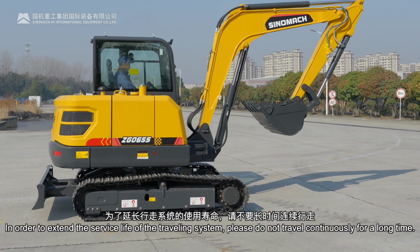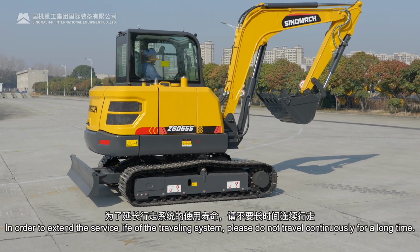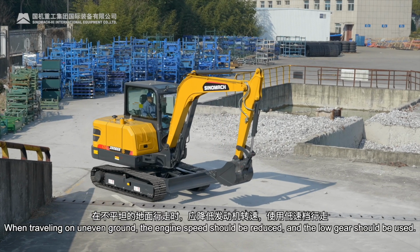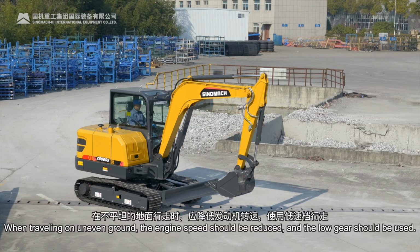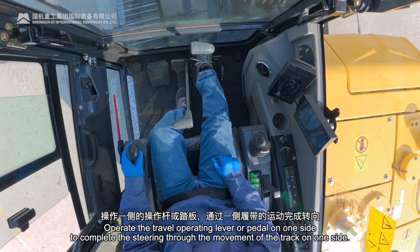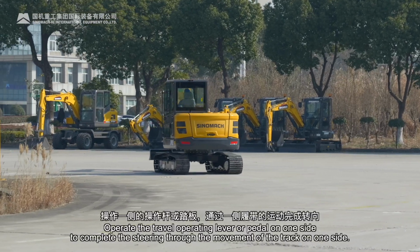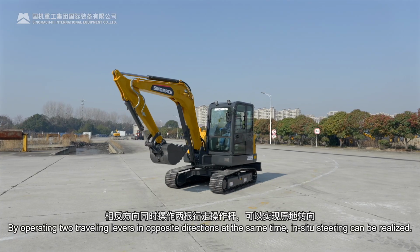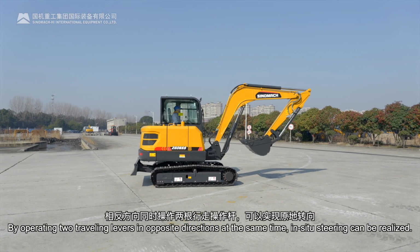In order to extend the service life of the traveling system, please do not travel continuously for a long time. When traveling on uneven ground, the engine speed should be reduced and the low gear should be used. Operate the travel operating lever or pedal on one side to complete the steering through the movement of the track on one side. By operating 2 traveling levers in opposite directions at the same time,